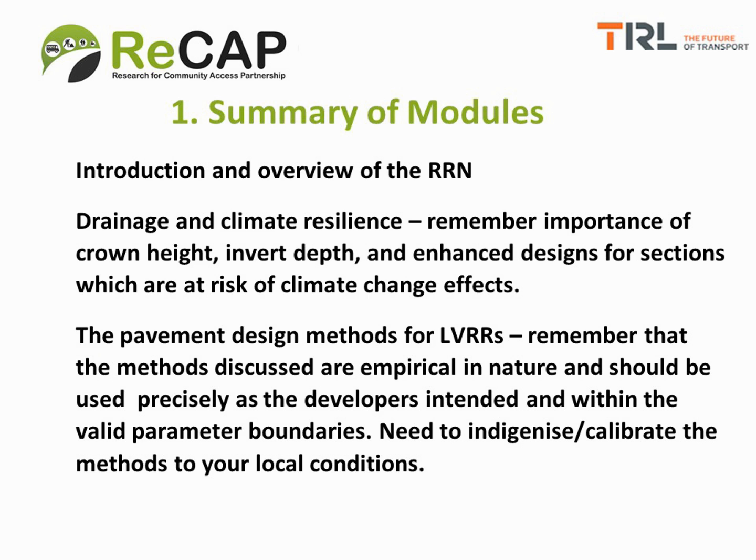Now we shall recap the 6 modules that you covered as part of the training. The first module was the introduction and overview of the RRN, which looked at what the RRN contained. The second module was on drainage and climate resilience. And here we want you to remember the importance of aspects that affect pavement drainage, such as crown height, invert depth, and the need to use enhanced designs for sections which are at risk of climate change effects.